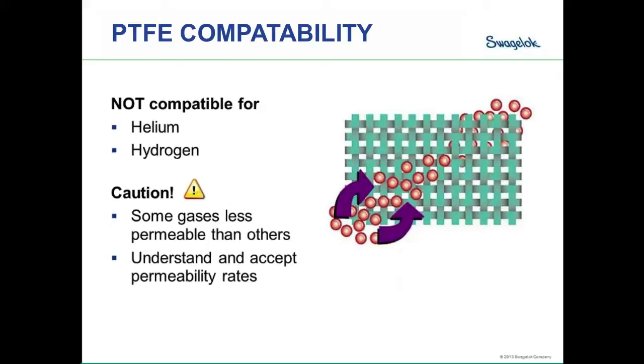Well, the reason that happens is the helium is a really small gas molecule, as is hydrogen. So those small gas molecules will find their way through the balloon. So if the balloon's a rubber or some sort of mylar material, over a period of time, those gas molecules escape, and then as one does, another one follows behind it, and so forth and so on. The same thing happens with hoses. So, for instance, if we were looking at a Teflon hose being a plastic, it's highly permeable. So as you can see from the picture here, these would be the gas molecules, and under a microscope, if the Teflon material had gaps like that, these molecules would find their way through.